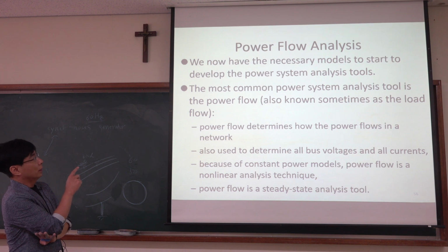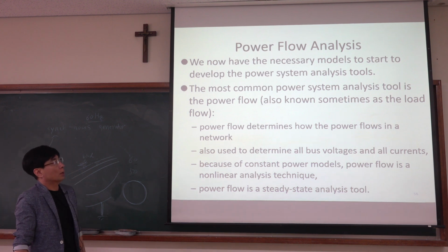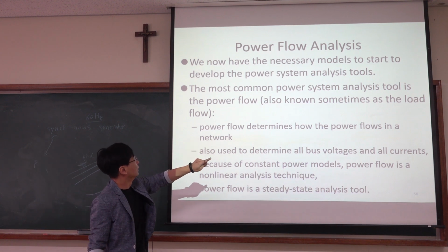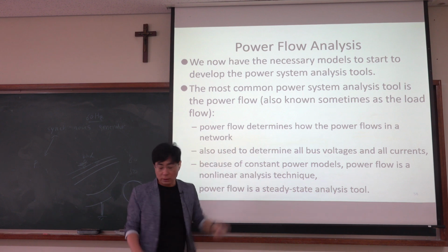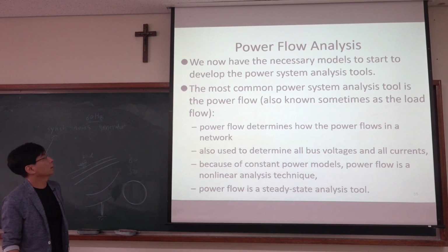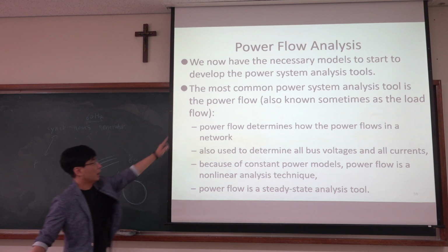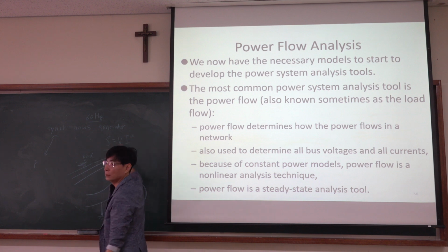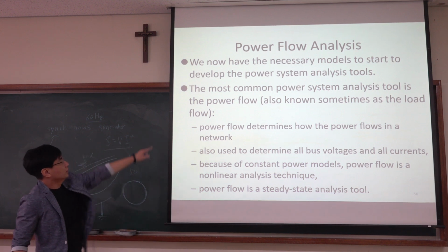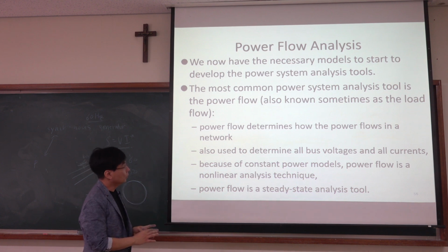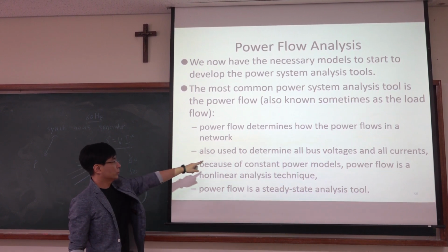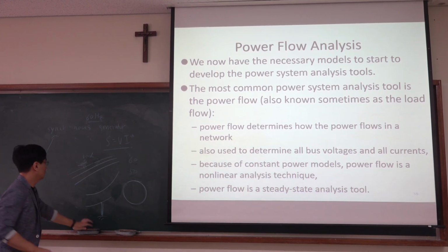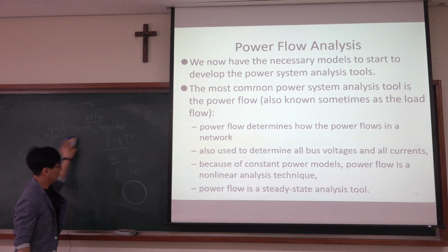We now have the necessary models to start to develop the power system analysis tools. And the most common power system analysis tool is the power flow. Sometimes that was called load flow, but we typically use power flow terminology. So what is power flow? S equals V times I conjugate. Power flow determines how the power flows in a network, and is also used to determine all bus voltages and all currents.